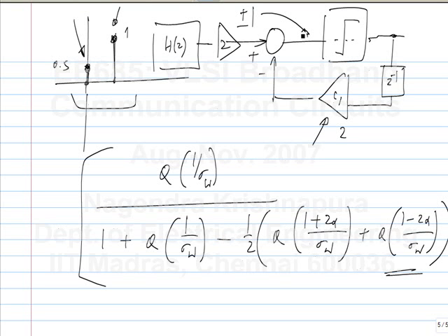It will amplify the noise. So if you treat the small element as the cursor, you will have to amplify it to the right level. Or if you don't amplify it, again, this plus minus 1 is a kind of arbitrary thing. I can always say plus minus half is my logic 0 and logic 1. But then in that case, for a given noise variance, it's a smaller ratio, right? So you will get a larger error rate. So if you think of this as the cursor and equalize it, you are cancelling the large part and you are left with the small one, you will get a larger bit error rate. Is this part okay?